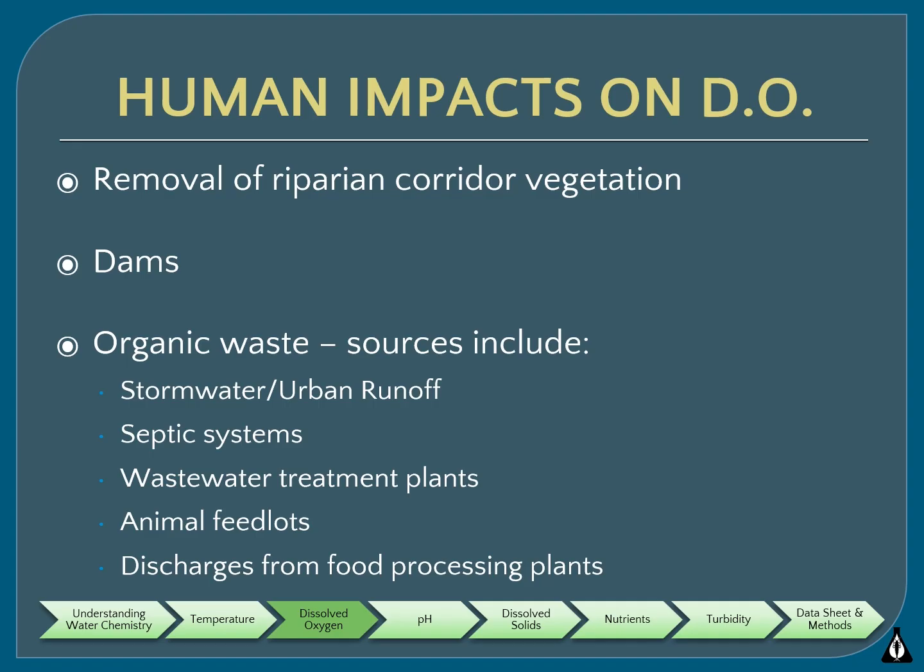But on the other hand, if the water comes from the top layer of the lake, this might be high in dissolved oxygen. In this case, the addition of more oxygen as it tumbles over the spillway can cause the water to become supersaturated. Too much dissolved oxygen can actually kill fish by causing the same symptom as the bends in divers when they ascend too quickly. If a dam is discharging into a water of the state, they have to meet water quality standards of 5 milligrams per liter at least whenever they discharge.